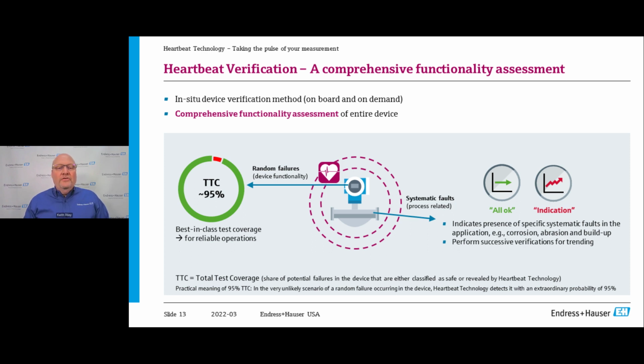All right. It also can take place in situ, meaning the instrument is going to stay in service in the process, and it's also not going to interrupt the output to the control system. So you can run a verification at the same time that you're continuing to get measurement information back at the control system.